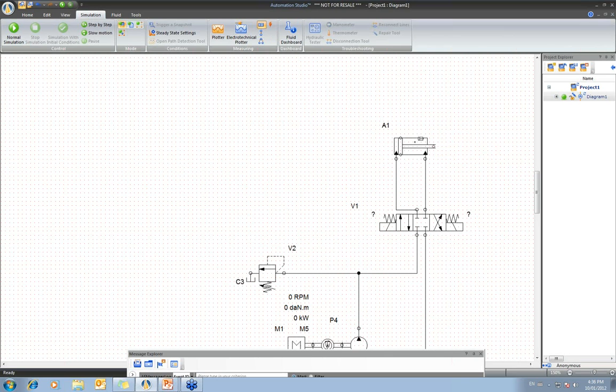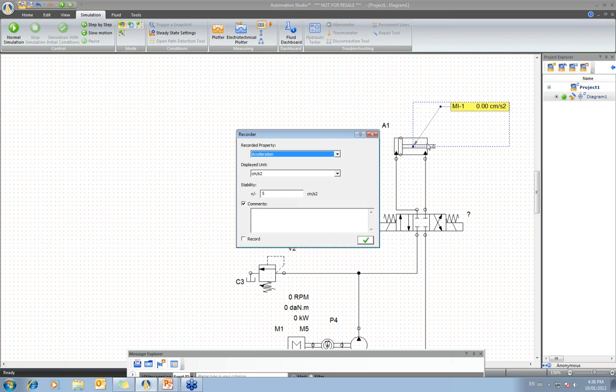You can simply move over these components. Once you pick the component that you want to collect information from, you click again where you want to start the leader. Once you have started to create your leader, you hold your click and move to whatever location you want. Once you are in a proper location, you simply release. Once you release, you will have access to different parameters.